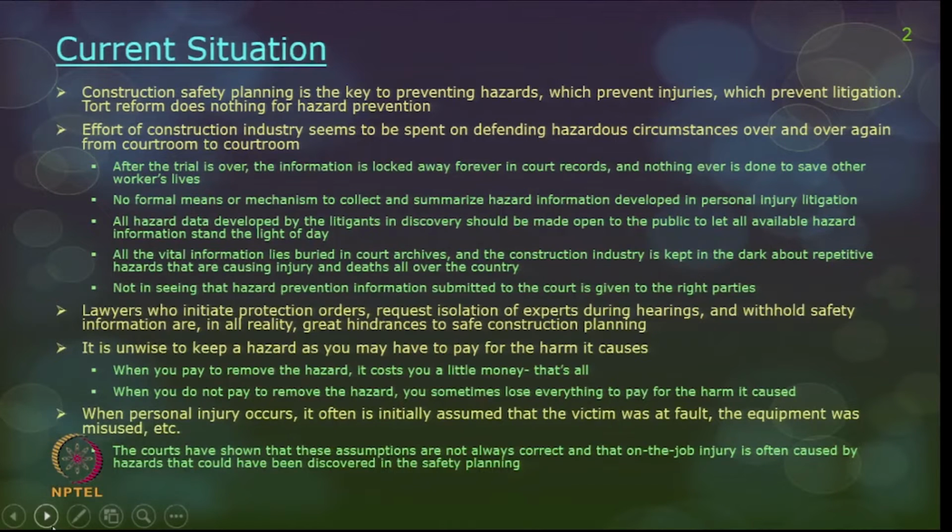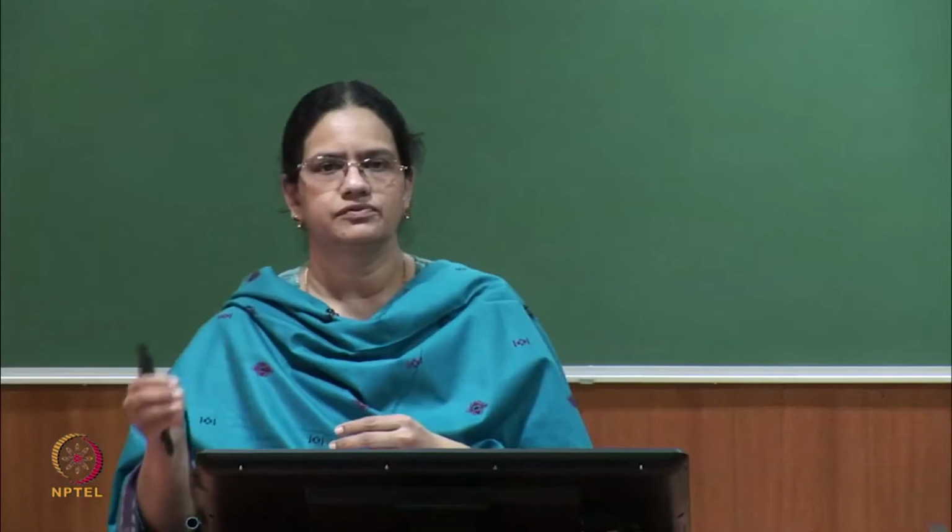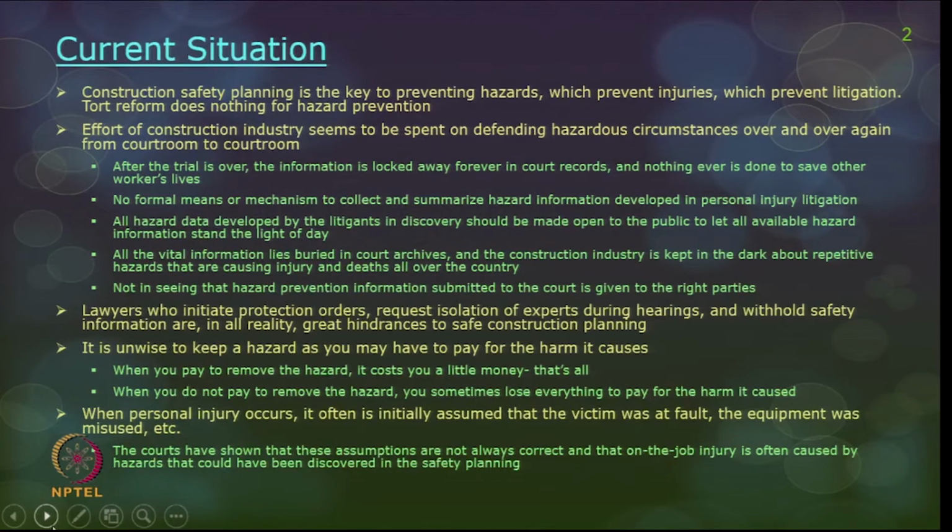So, what is the current situation? Most of the accidents happening today, as we discussed in the chain of events theory or domino theory, are attributed to one factor, wherein a person was identified as the causal factor. But if you start analyzing the root cause of the accidents, the direct, indirect, and tertiary causes and so on, it would be some management situation or some hazard present in the project and the construction site which made the worker behave in a different way and resulted in an accident. You would have noticed this when we discussed the theory long back.